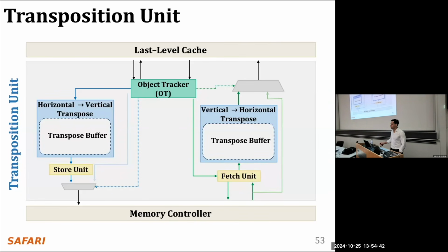So, sure. About the triple carry adder, at least in the slides here, you're computing the carry, but the same A, B, and carry-in also need to be used to compute the sum. Yes, yes. Now you have destruction of the data. Yes, yes. You have to again copy the data for computing a single sum bit again. So we don't compute it twice.